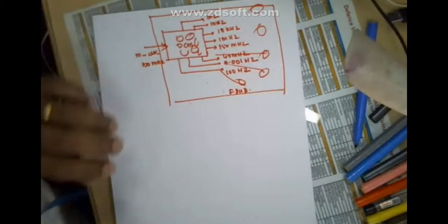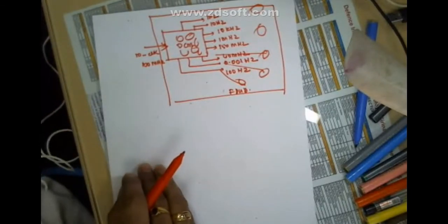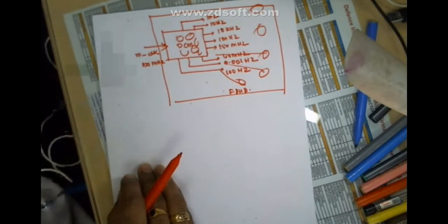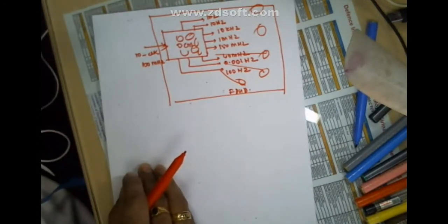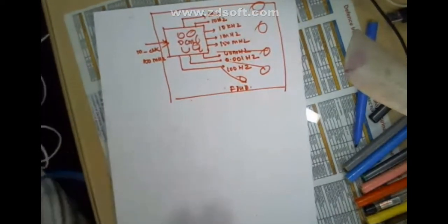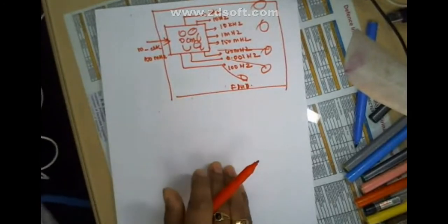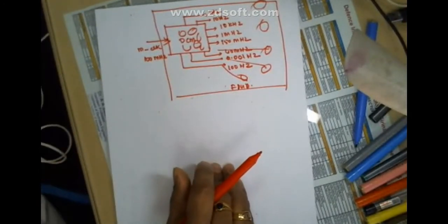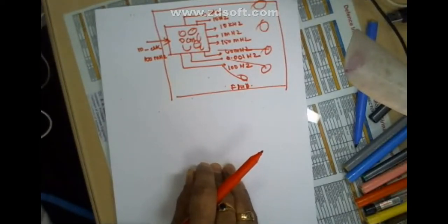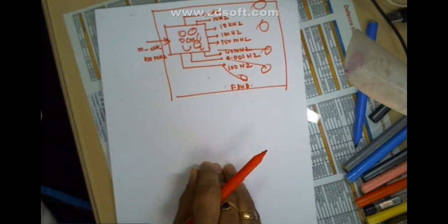The idea is your master clock should be applied to the DCM, and then you make the DCM generate the required clocks. Then all your other computation modules or sub design units will be operated with respect to those generated clocks, the appropriate clock, right? As we progress, you will be familiar with choosing the clock. Suppose for an LCD, what clock rate is needed, for a 7 segment display, what is the clock rate, for a GLCD, what is the clock rate? All those things are available in the product data sheet or in the user manual. So you need to generate that clock rate to operate them.